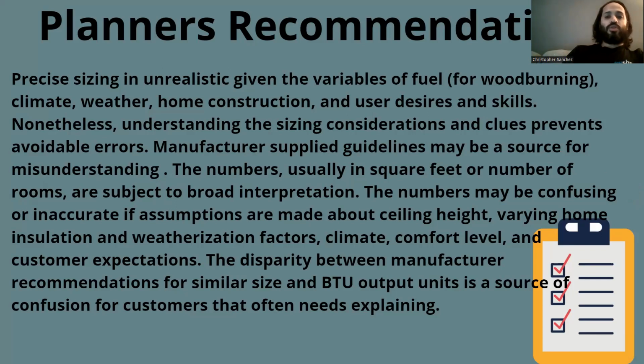The numbers, usually in square feet or number of rooms, are subject to broad interpretation. The numbers may be confusing or inaccurate if assumptions are made about ceiling height, varying home insulation and weatherization factors, climate, comfort level, and customer expectations. Disparity between manufacturer recommendations for similar size and BTU output units is a source of confusion for customers that often needs explaining.